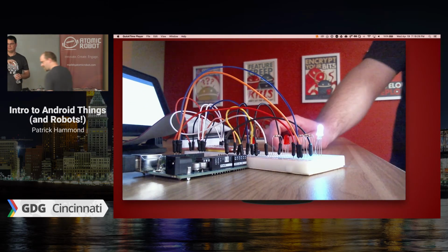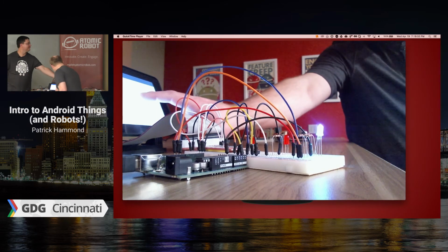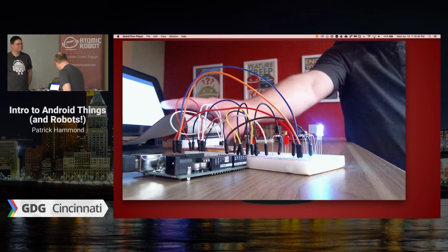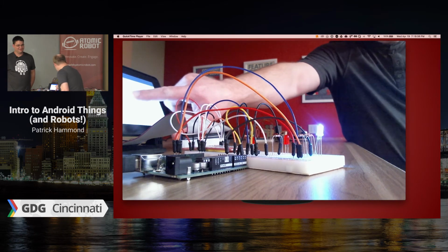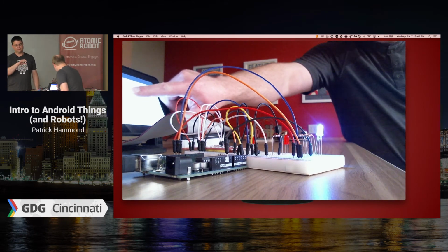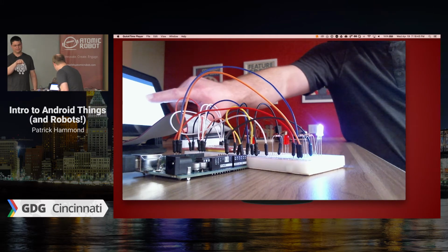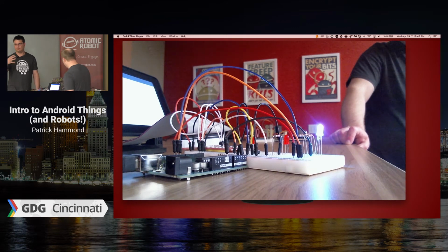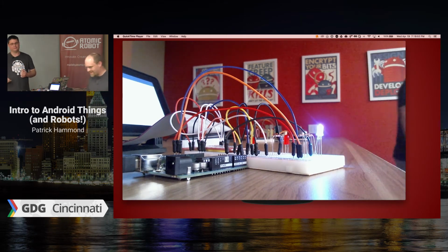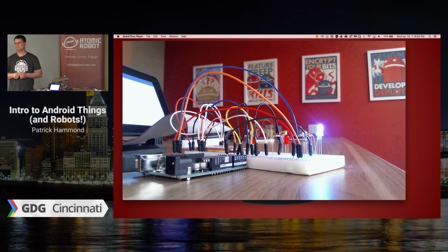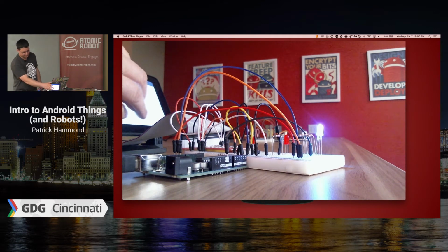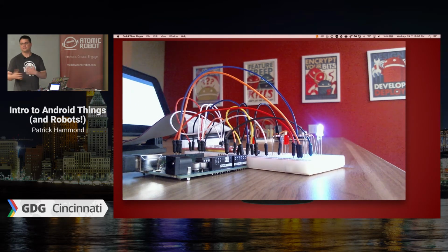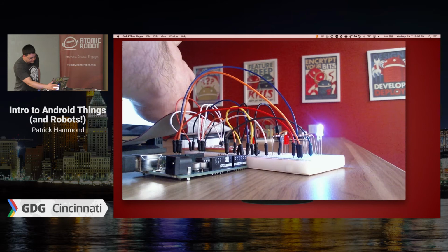Can everyone in the back see this thing lighting up and changing colors? Whenever he's changing this, we're going through and reading the values off the sliders and sending those to the Arduino, which is then pumping out values to the pins on it. The same pulse width modulation pins that it has to control the color of that LED. What's the top slider? The top slider is what we had before. It controls the brightness of the LED that we had before. So these are all building upon each other. Okay, so that's all fun. I'm going to turn it off because that's really bright in my eyes.